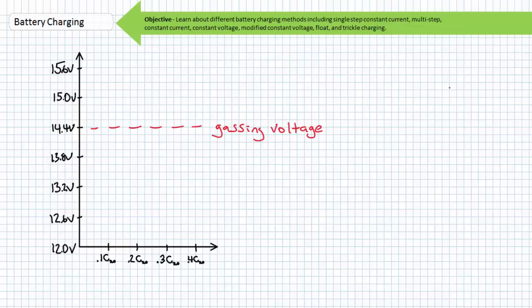A common maintenance task associated with flooded lead-acid batteries is the periodic addition of distilled water to compensate for water lost to gassing. "Maintenance-free" batteries, by the way, I'm using quotation marks with my fingers, solve this problem by catalytically recombining the gases into liquid water, over-provisioning the electrolyte, or other methods to prevent progressive loss or degradation of the electrolyte effectiveness. By monitoring the battery voltage, the charge process can determine when the battery off-gasses.